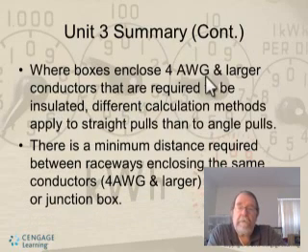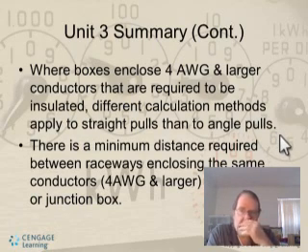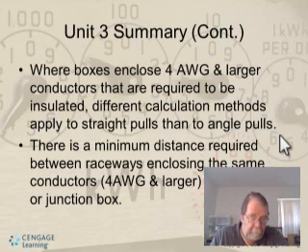Where boxes enclose 4-gauge or larger conductors that are required to be insulated, different calculation methods apply to straight pulls than to angle pulls. There is a maximum distance required between raceways enclosing the same conductors within a pull box or junction box.